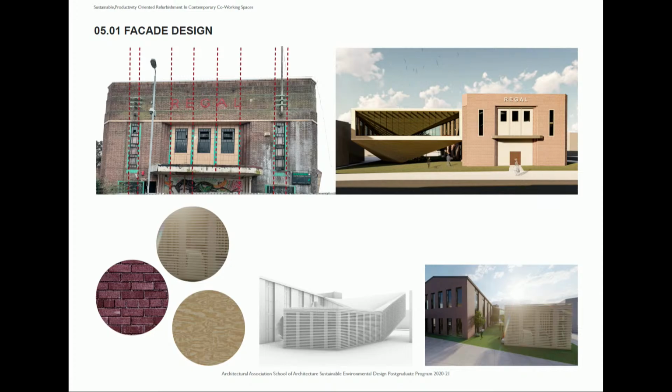And in addition to that, when I did the simulations for the new built place on the south facade, I saw that since there are no other elements providing shading and reducing the solar radiation, the south facade and the east facade are having too much solar radiation. So in order to reduce the solar radiation in the new built part, I wanted to create some horizontal shading elements to create a more comfortable and more productive space within the new built element, while the existing structure has a really deep plan, so it can work and create comfortable environments without the shading elements.